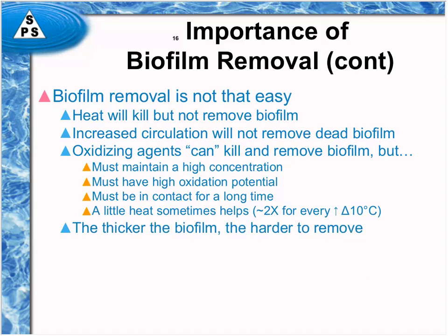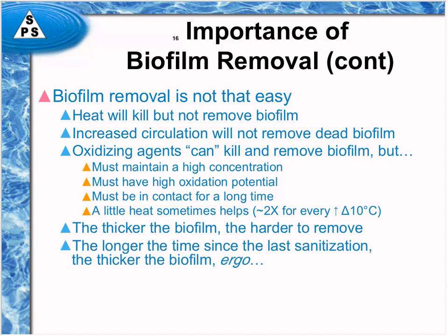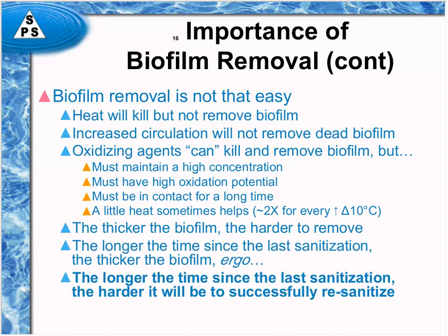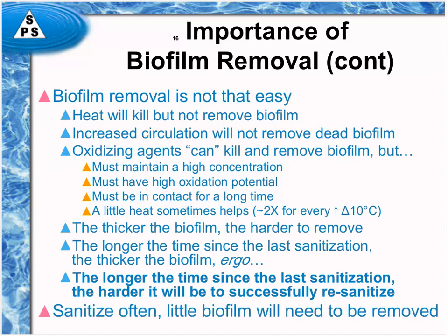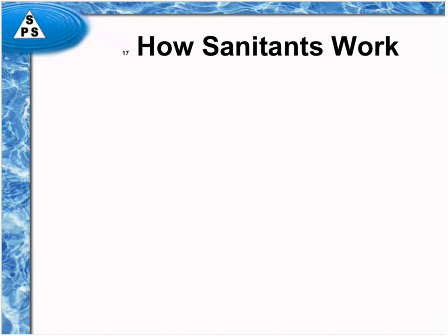The thicker the biofilm is, the harder it is to remove it because there's more that has to be removed. And the longer the time since the last sanitization, the thicker the biofilm will be. Therefore, the longer the time since the last sanitization, the harder it will be to successfully resanitize a water system. It's a very, very important concept. If you sanitize often, there will be little biofilm that needs to be removed, and it'll be easy to do.